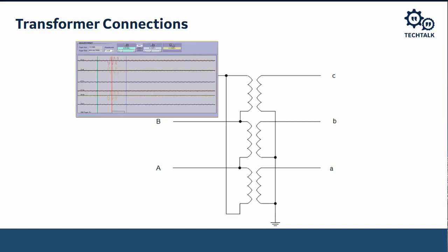And so if we look at the way this transformer is made, what's directly in phase with the B phase current on the secondary, that would be little b on the screen here, we go through that winding, it is exactly in phase with the winding that's right across from it. And that winding is made up of a combination of the B phase voltage or current and the A phase voltage and current. So from the way that the transformer is connected, it creates what we should expect to see for that B to ground fault on the secondary of the transformer. We should expect to see an increase in B phase current and A phase current on the primary of the transformer, which is exactly what we are seeing in this oscillography record.